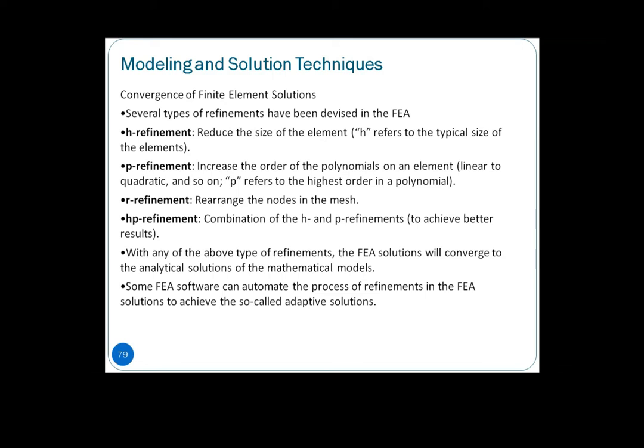In this refinement, if you are using higher-order polynomial functions, from linear to quadratic, you are increasing accuracy. Here we call it P refinement.